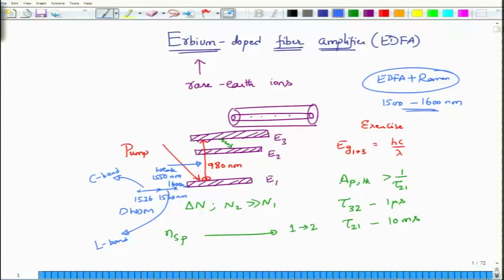Okay. So, anyway, the erbium doped fiber amplifier itself has a gain cross section that goes roughly from 1526 to 1560. These numbers can slightly change depending on various factors, but this is the range over which you are actually supplying the weak optical signals here. And what will these weak optical signals do when you launch them with a certain launch power of P in?